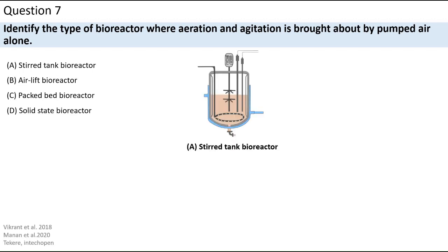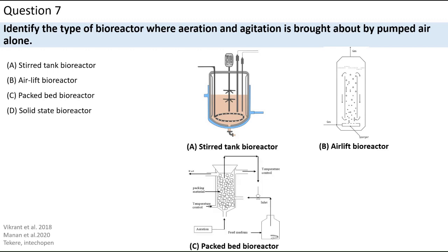So when we were seeing the stirred tank bioreactor, aeration is brought by the sparger and agitation is brought by the impeller. Whereas in the airlift bioreactor, both mixing, that is the agitation, as well as aeration, is brought about solely by pumped air alone.